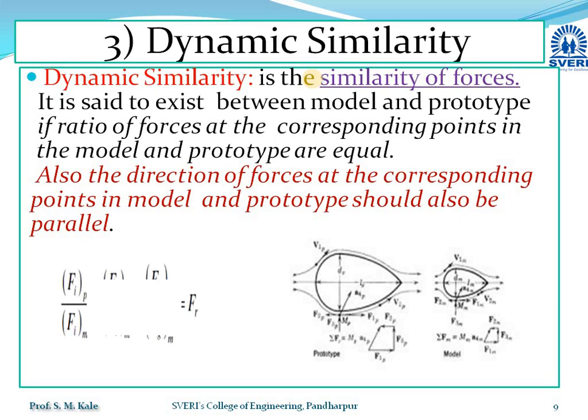So similarity of forces. If I consider Fi as the inertia force, Fv as the viscous force, Fg as the gravity force, and I take these various forces at various points in the prototype and at the corresponding points in the model, and the ratio of all those forces in the prototype and model is the same, and these various forces are acting in the same direction, that means they are parallel, then I am going to say that there is a dynamic similarity.